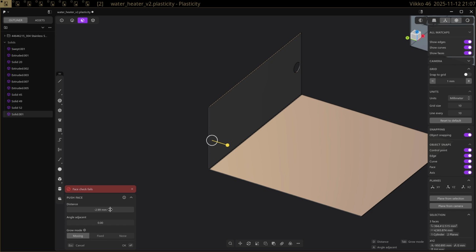It's in the negative direction to push these towards the neutral axis, so we need to have the length be negative here. So let's put a -1 at the start, then times the K factor, then the material thickness, so times 2.